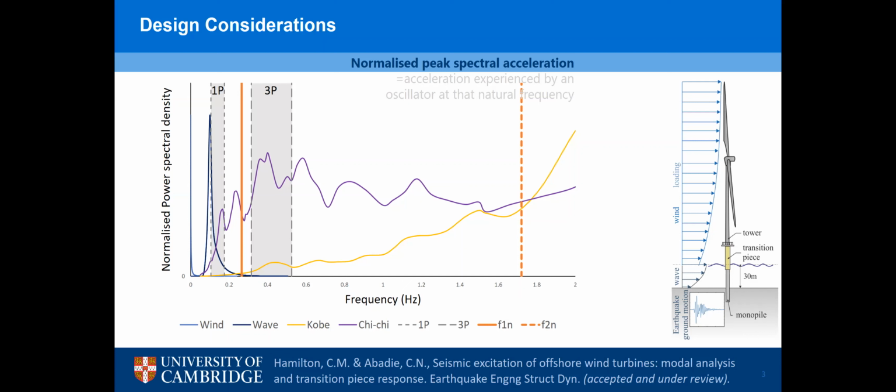And the one in dashed line is the second mode of the turbine, and there is a debate as to whether this mode is going to be excited and whether we need to worry about it. That sets the scene as to one of the concerns we have, which is whether the design we're doing is sufficiently robust in terms of frequency, and how can we adjust the soil frequency so that it's not too bad.